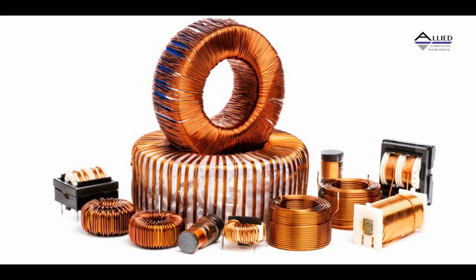Choking the airflow. When the choke is engaged, it partially or fully closes the carburetor's air intake, reducing the amount of air entering the combustion chamber. With less air, the fuel mixture becomes richer, a higher ratio of fuel to air. Warming up.